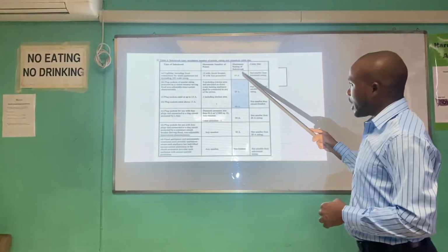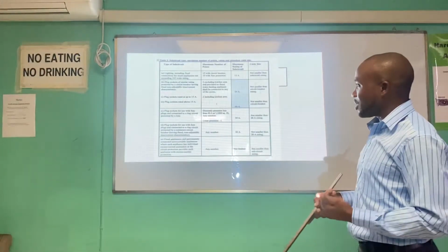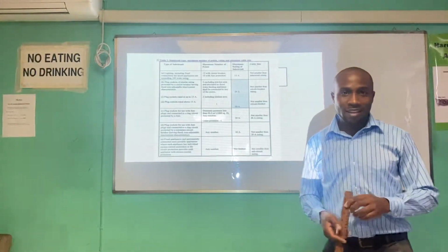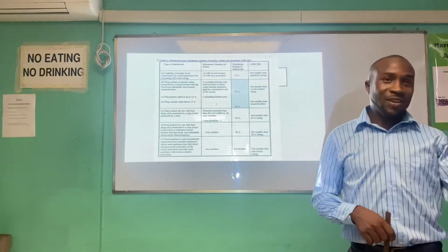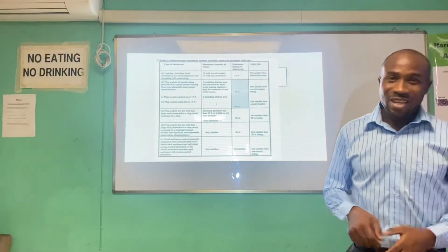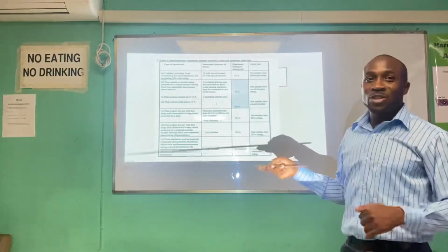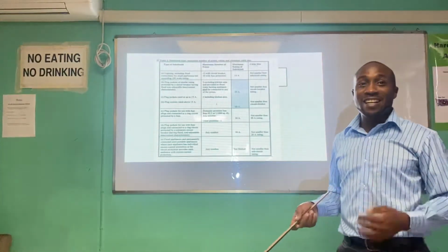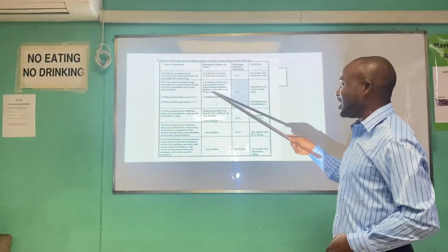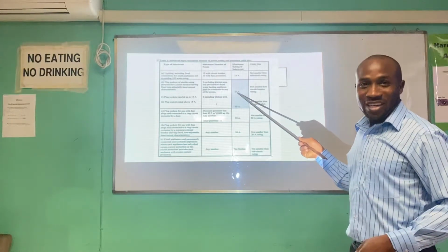Right, so these are the 2 main components. Whenever you look at an electrical panel and you see a lot of 20 amp single pole breakers, you know that if the electrician did the installation according to the regulation, these would be plug circuits.